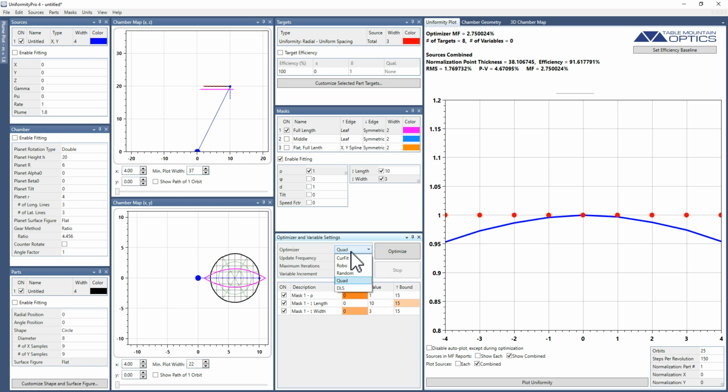So they just give you different methods to perform optimization. The parameters for all of the optimizers are constrained to the specified bounds, which I'll talk about in a second. All of them have a step size, which is a really important thing for you to be adjusting when trying to find more optimal solutions. So let's start out with damp least squares for now.